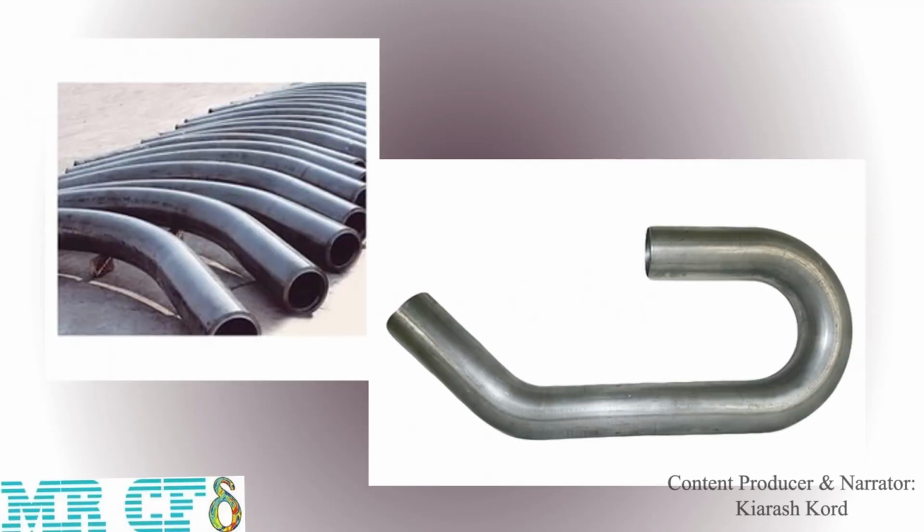In this project, the compressible flow inside the bent pipe is simulated and the shock wave is investigated. 5 degree air enters through a pipe inlet with 0.9 Mach number. The extreme pressure gradient causes a shock wave. The mesh grid needs to be refined to capture flow ideally at high gradient zones. Therefore, we can use the gradient adaptation option in ANSYS Fluent.